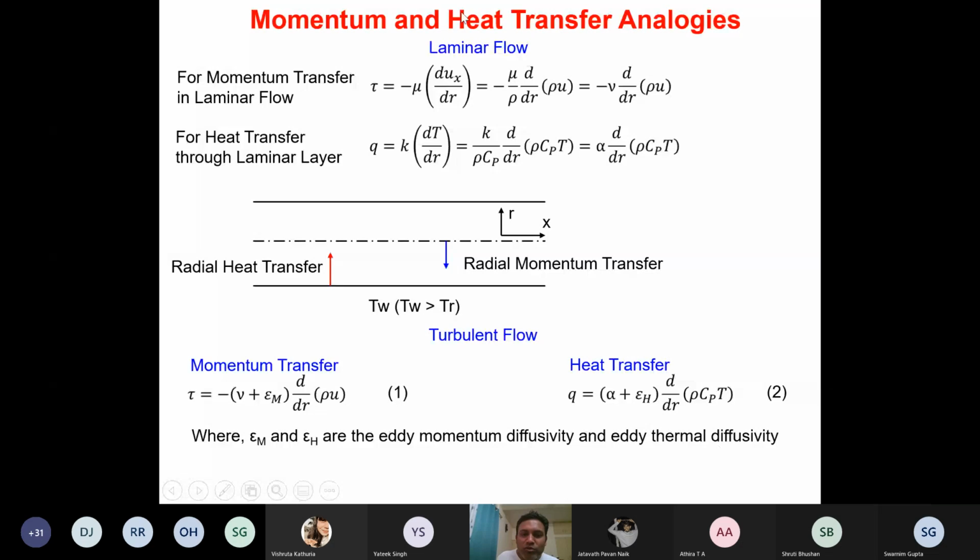But essentially we have assumed that the entire flow in this cross section of the pipe is turbulent, but that is not the case, isn't it? The fluid layer which is very close to the pipe wall is going to be stagnant, and the layer nearby to that is going to be laminar, isn't it? You are going to have a laminar flow there.